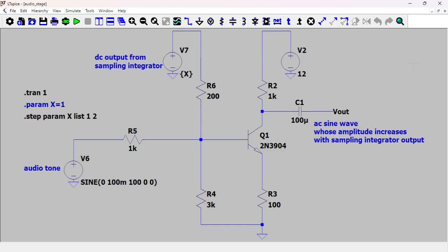And what's the role of that audio stage? It's to transform that DC output voltage, or near DC, to a sound that gets louder as you go nearer to the target. So when you swing, if you don't have any metal under your coil, no sound.